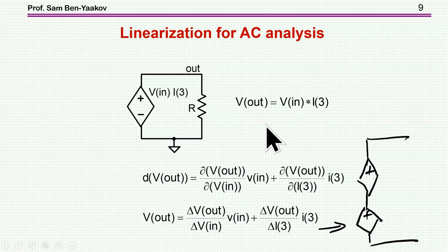So in this case, it will be the partial derivative of this thing, the V out, with respect, say, to this variable or this parameter, and therefore we are getting a constant times the AC component or the phasor component in the two cases here for the two derivatives. Now, in the case of a numerical simulator, of course, this is done numerically. So we are talking about the ratio between differences. Okay, this is the local derivative, and this is the AC component.